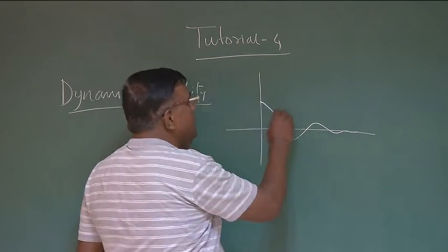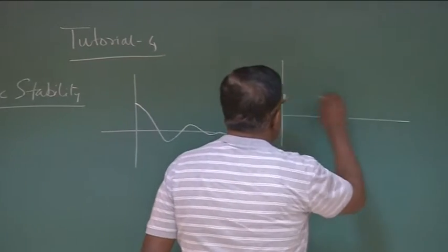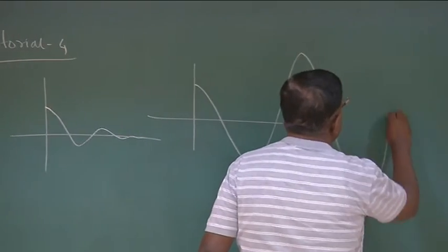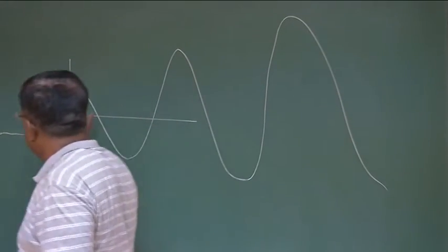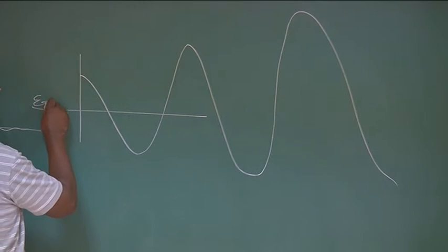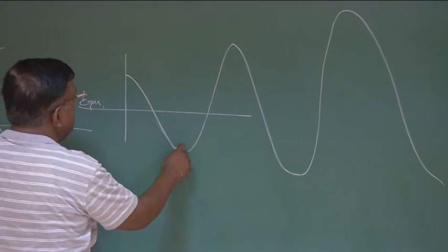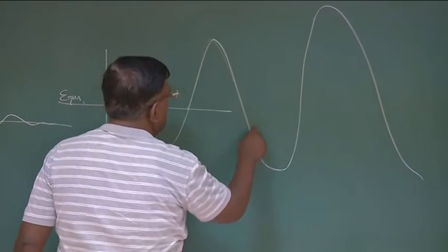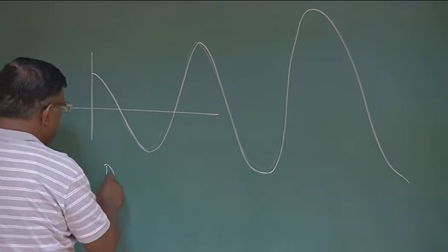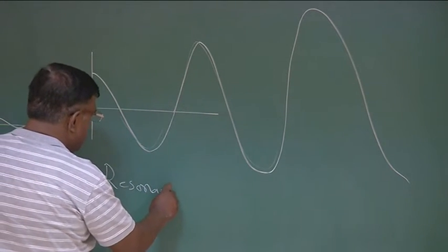It's possible it has the initial tendency to come back, but every time it is further going up and up like this. So you could see it has got the initial tendency as soon as it crosses the equilibrium. Say this is equilibrium, it goes, again it tries to come back to equilibrium, again overshoots, and the amplitude goes on increasing. So this is a typical case of dynamic instability. And typically, you know, this is a phenomenon close to resonance, right?